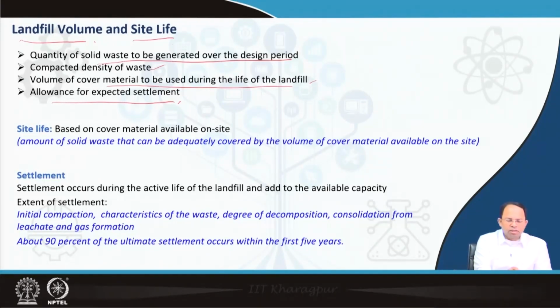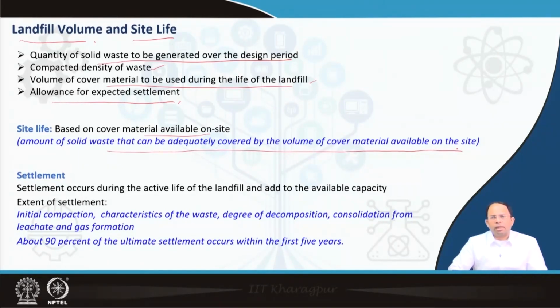The site life is based on the volume of cover material or soil, or the amount of solid waste that can be adequately covered by the volume of cover material available on the site. So this could be one of the criteria for determining the site life of that particular landfill site.